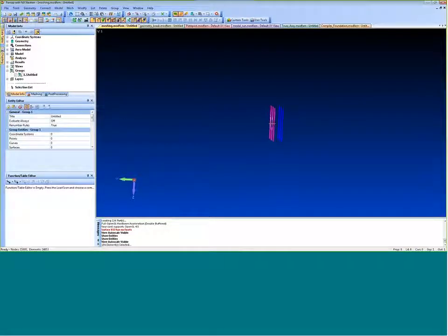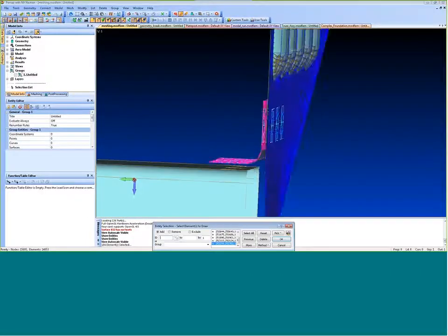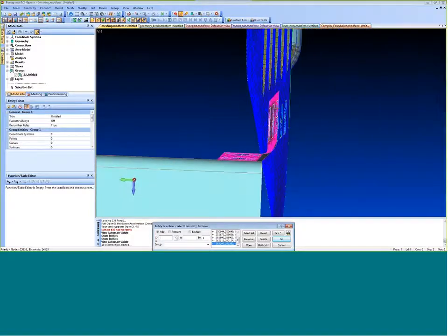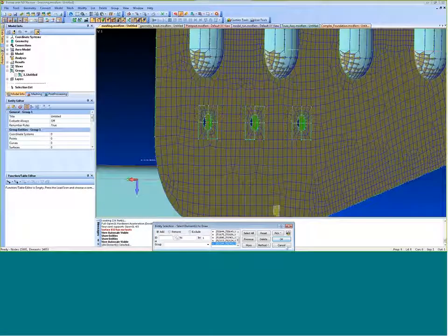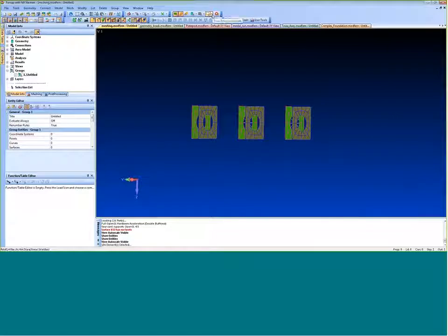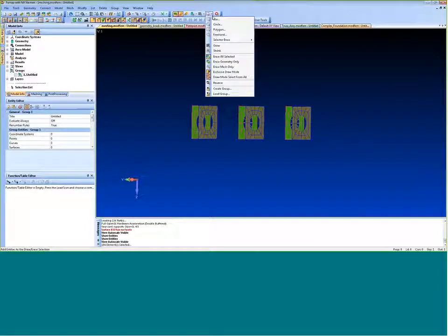Unfortunately, I have more than I wanted. I got the other side of this. Historically, when you would do this and you would want to reselect to get a smaller group, you do select elements and everything would show again. Sometimes it's not really what you want. So now this new feature is you can go to this draw erase selected area drop-down menu and deselect the default, which is draw mode select from all.